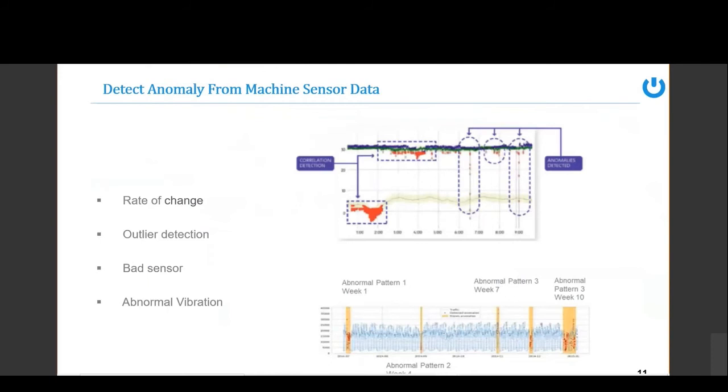For example, when a centrifugal pump in your water treatment facility shows abnormal vibration, it also directs you to the contributing parameters for that particular fault. It may be the x-axis RMS value or high bearing temperature, and this specific information helps you prioritize your work order.